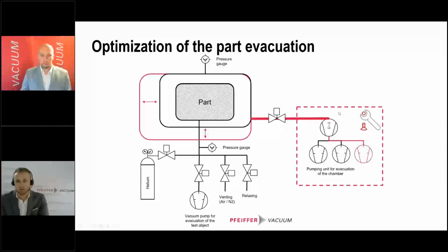So the pumping of the chamber lasts much longer than the pump down of the part, because the inner volume of the part is much smaller than the free volume of the chamber. But in the end, after a successful leak detection process, you have to clean up your part again from the helium which you inserted. So at some point, the pump down time of the unit you test is also important, not only for the contamination reduction, but also for your overall cycle time.